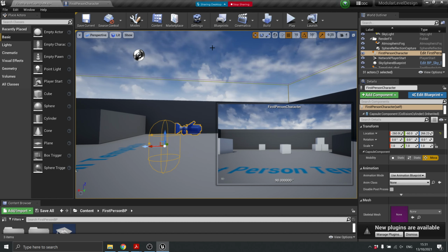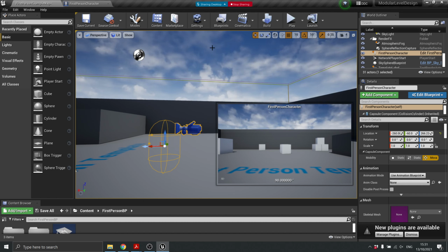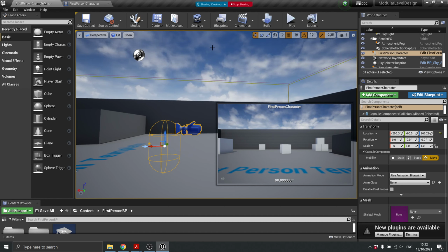Okay, and your 8 foot is basically floor to ceiling, and your 4 foot is the width of the board basically on the wall. So, somewhere like that is about 4 foot, and that's one of the panels. The reason they do that for housing is that it's cheaper. If every panel is the same size, you're doing less cutting and everything kind of slots into place.